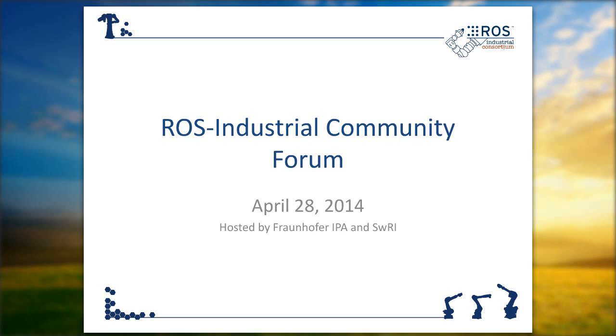There was also another question on ROS control, which was how are the real-time parts actually implemented? I would like to address that one as well. So actually, ROS control does not make any assumptions on whether there is a real-time operating system in place or not, and if there is one, which you are using. So in fact, that's up to you. If you want to use Xenomai or VxWorks or the RT preempt patch, it's up to you to set that up and then wrap the ROS control code inside a thread that has real-time privileges.